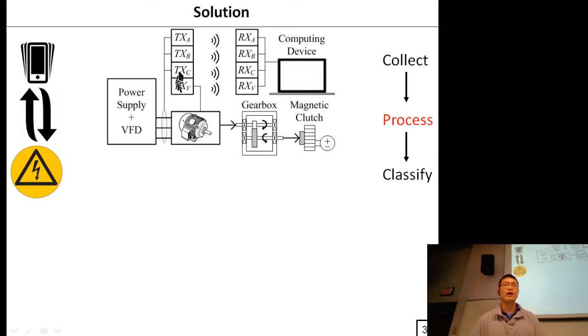Where I have an induction motor and 3 smart sensors collecting current, one for each phase of the current, and one vibration smart sensor whose job is to track the rotor speed. Connected to a gearbox, the same gearbox that many publications say cause problems, and a magnetic clutch to adjust the loading of the induction motor.